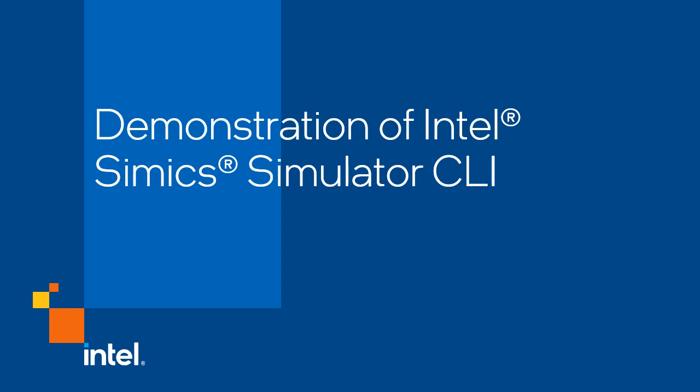End the command line capture by using stop command line capture. Now the file has been saved with the changes and capture of the Intel Simics CLI. Explore many other options and capabilities of the Intel Simics Simulator and CLI in the user guide link provided in the resources. Now that we have the Intel Agilex 5 SoC FPGA booted to the embedded Linux OS, we can say hello SoC FPGA, as we will do it using the actual hardware.